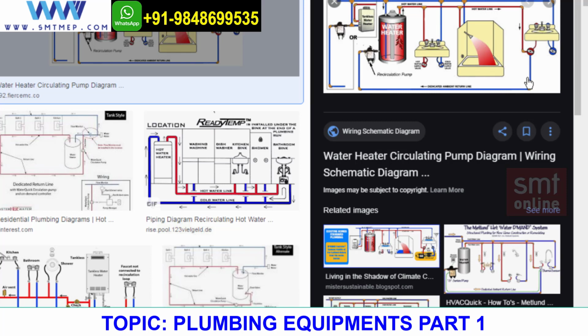Or else, as you people might have experienced, if we don't have a hot water circulating pump, we need to wait a certain amount of time till the cold water is drained from the hot water line. When it is drained, I'll get hot water. So to avoid all this, the hot water will always be circulating round and round through the complete piping. Anyone calls, and the water is available right away. It is passing through those fixtures only.